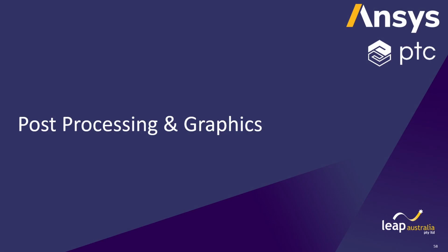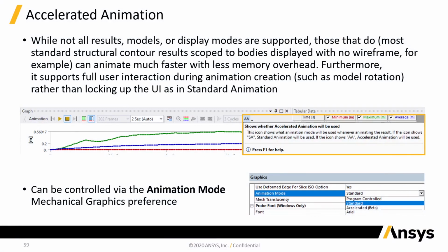Okay, post-processing and graphics, a little bit about that. Yes, the animation has been enhanced. Again, this is very handy when you have very large models and you want to create animations, or if you have highly nonlinear or very heavy transient simulation with lots of time steps, big models. Animations, they can take a lot of time to generate, and use a lot of memory as well. And if you go to the options and go to the graphics display and select animation mode accelerated, which is a beta version at the moment, you get much faster behavior.